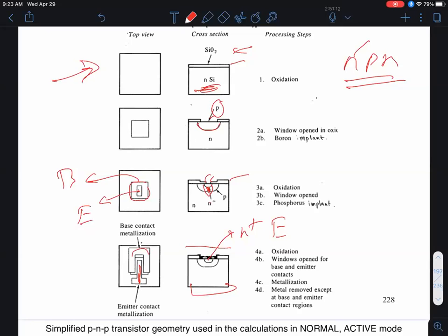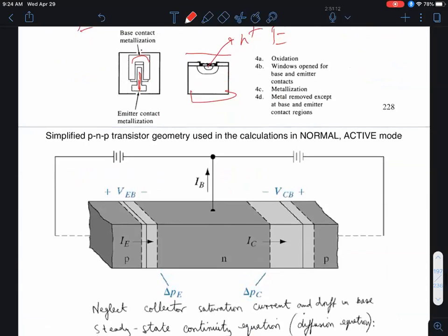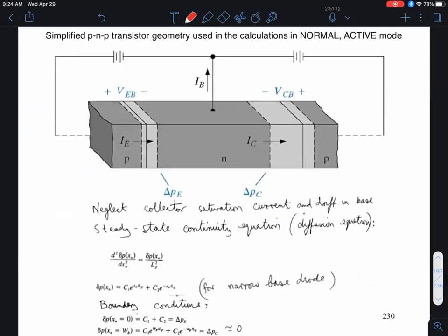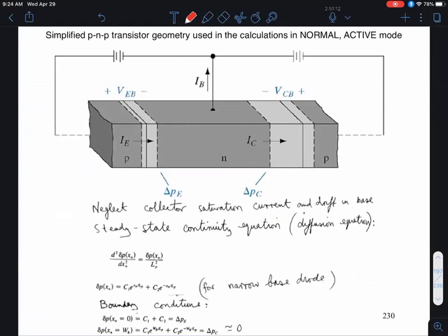Similarly, suppose this emitter rectangle gets very close to the base rectangle. In the lateral dimension, you get a breakdown, right? So you have to have the emitter window nested within the base window, okay? So those are the things that are done in a very clever way, in a self-aligned fashion, in a practical way of manufacturing BJTs that's described in section 7.1 of the textbook.